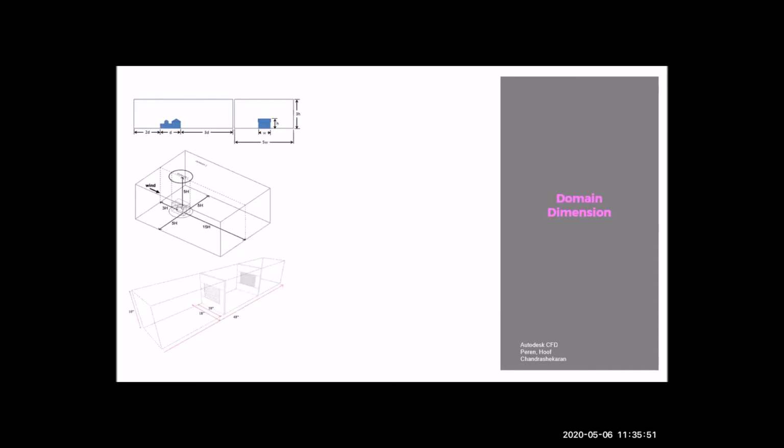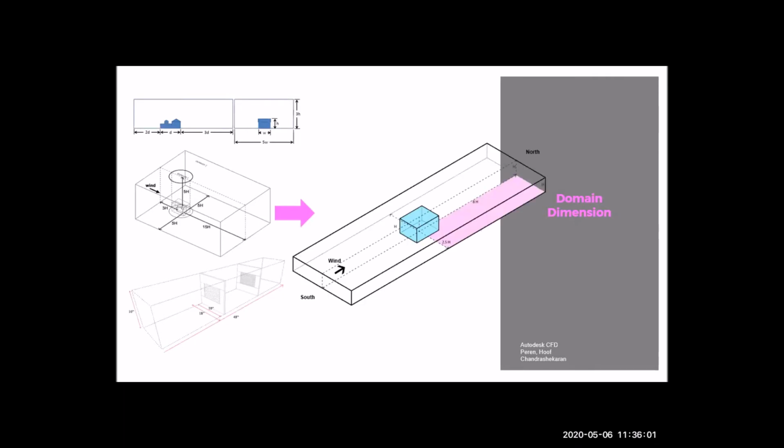Based on previous research, the computational domain is designed and reduced in scale to accurately simulate wind tunnel geometry. However, the height of the domain has been reduced to 1/3 of the room height to limit development of unintended streamwise gradient. The dimensions of the domain are 70, 240, and 15 feet in full scale, which will reduce the scale of simulation.